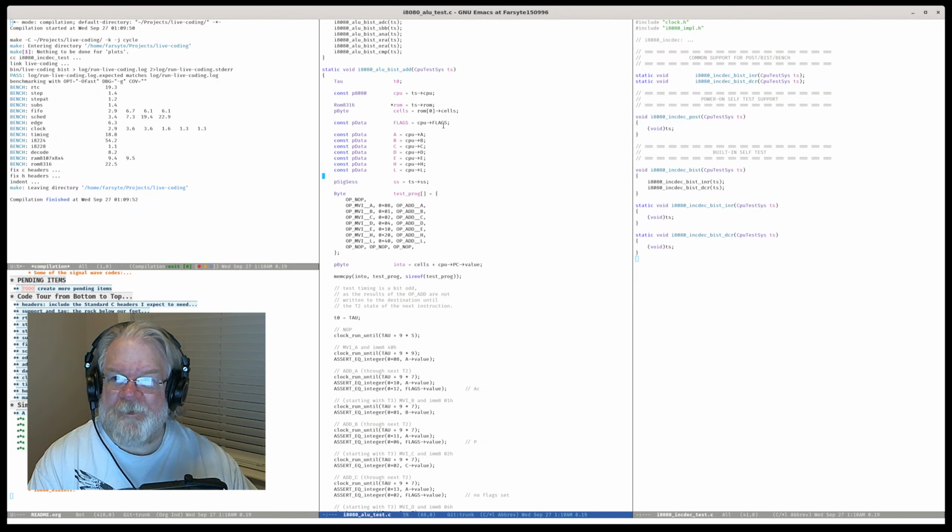So the typical pattern I've been following for these subtests is a prologue looks something like this, where I can have a little test program on the stack, copy it into memory, wherever the PC is, and start it running. And this depends on the PC pointing at the next instruction we are going to fetch, and it's not being in the middle of whatever when this happens.